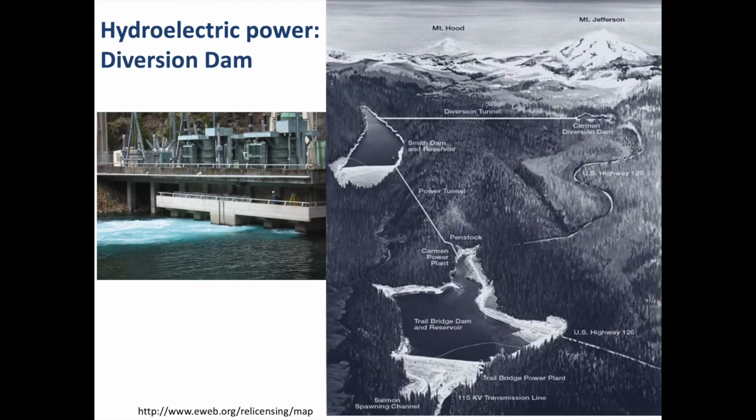On the previous slide, I showed you a classic impoundment reservoir where the dam is built into the river valley and water flows through the penstock and directly back into the river. There are two other types of hydroelectric dams worth knowing about. One is a diversion dam, like the system shown here. In a diversion dam, water is diverted through a pipe or canal to the turbine.